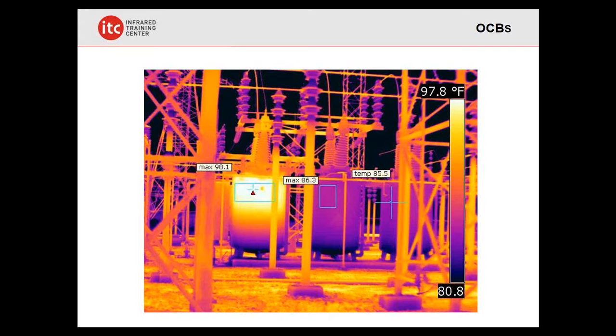And so in a situation like this, you learn that if you're seeing this with oil-filled circuit breakers in an outdoor substation, what appears to be a very subtle temperature difference between two of these OCBs is really much more significant. In fact, if it's this case, you could almost say it's probably game over at this point. Because of that, how much heating there is on the inside to generate even that little bit of a signature on the outside, Gary. Right. I mean, that heat generated at the contacts has to travel through all the oil, then through the casing to display on the outside.